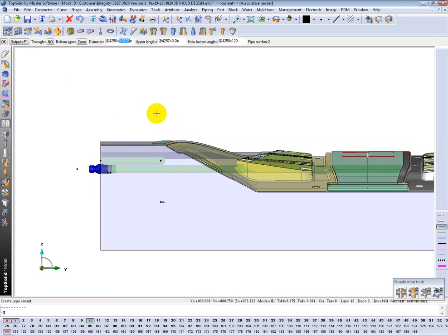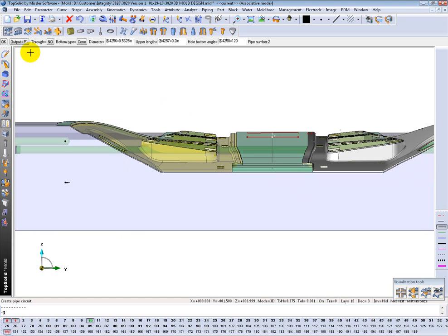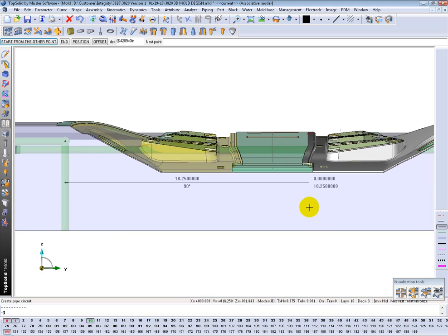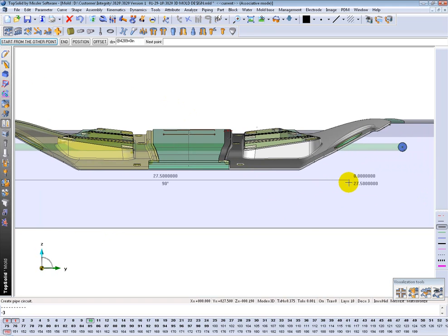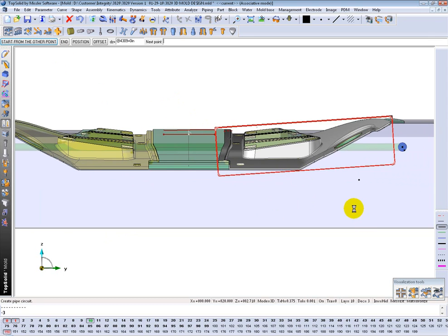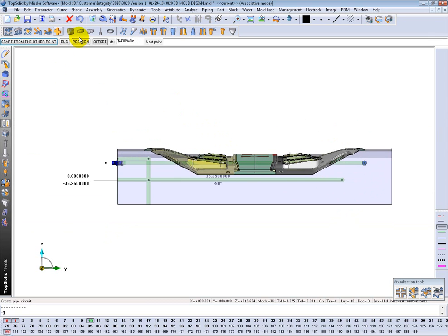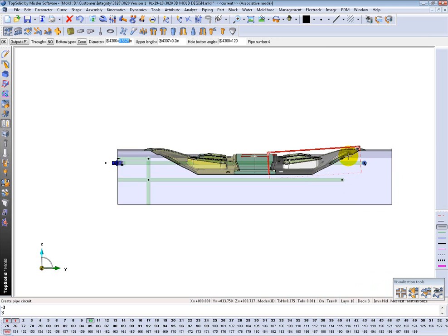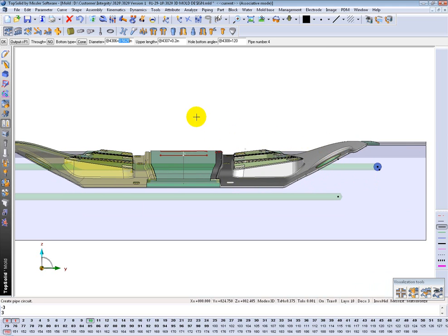So now I'm drawing at this point. Alright, my drill point's going to come out at point 2. I'll say OK to that. And then I'm just going to shoot across and maybe drill to this depth with my drill point 1. Say OK. And then I'll offset it back up to the 3-inch mark from here. And seeing where I'm at, I might interfere with that, but let's see what happens with the interference checker with top solid. Output point 1.